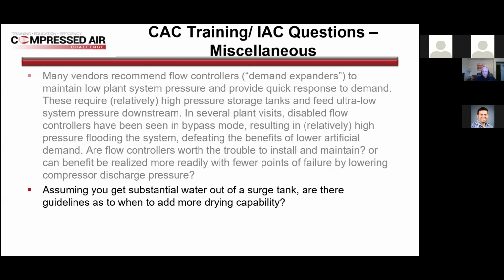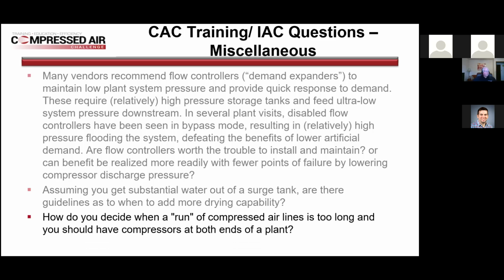As far as the dryers, I would look at things like pressure drop across the dryer. If it's gotten too large, or if you're seeing dew points way high and issues there, then I would start looking at the dryer. Or if it's a fixed load dryer where you've got low flows through it, that could cause an issue as well.